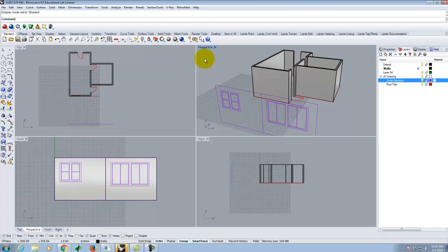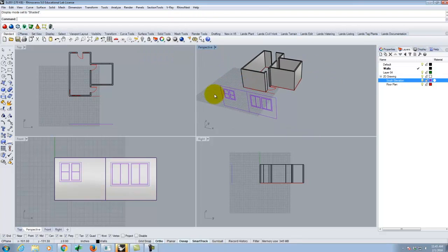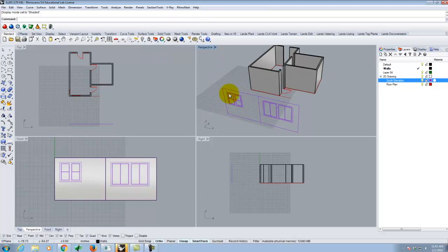So if I were in the perspective view, let's say something like this, and I typed project and I tried to project these lines onto these surfaces, the view goes straight into the screen like this, and so these lines wouldn't end up on those surfaces because they'd be projected straight. If, however, I initiated the project command in this front view, a straight line into the screen would take these lines and place them perfectly on the walls in this view.